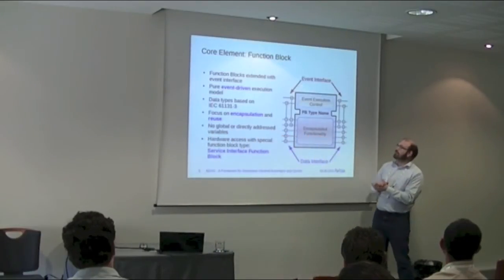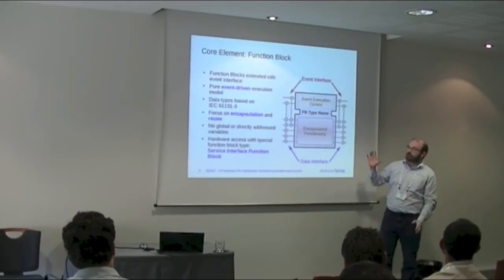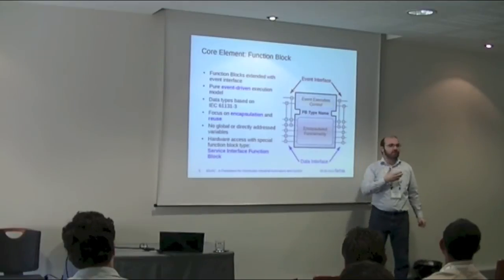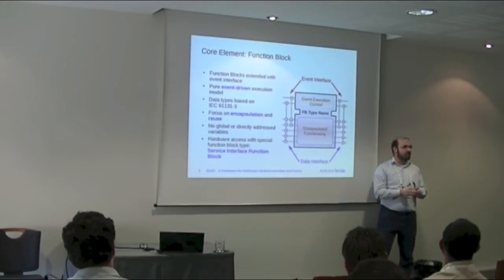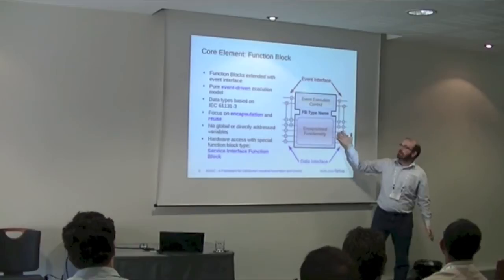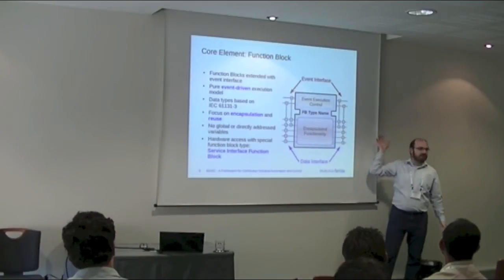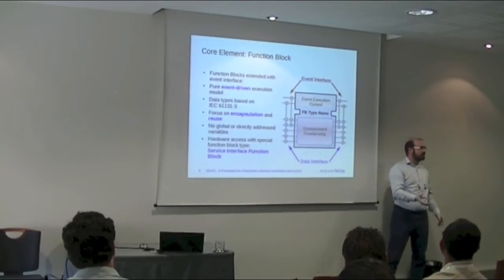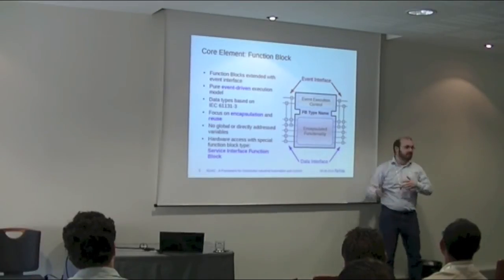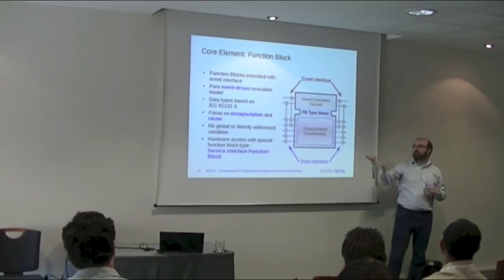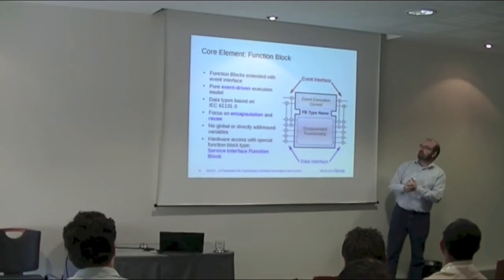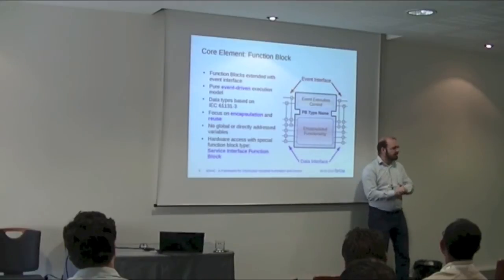Before 61499, what we had is also function blocks, but only function blocks with data interfaces. So we have these Simulink-like data flow languages where you have data input coming into the function block, which will be processed to produce data output. And magically, the system where this function block is put into will ensure that the data is provided, that the function block is executed in time, and that output data is given to the next ones. Typically it is done in a cyclic way, because then we know all about the real-time aspects, and this is how it has been done.